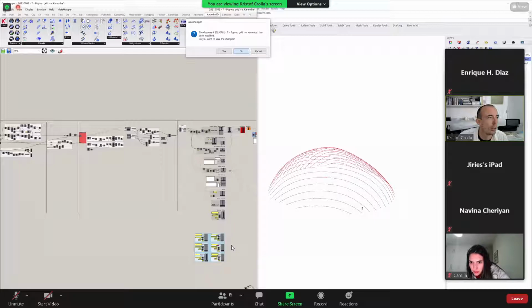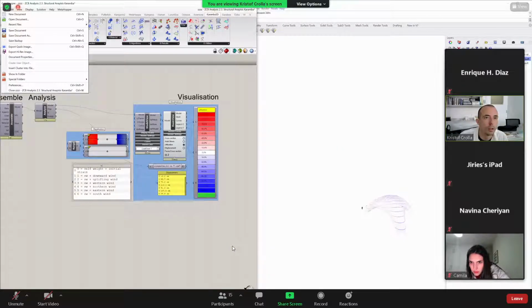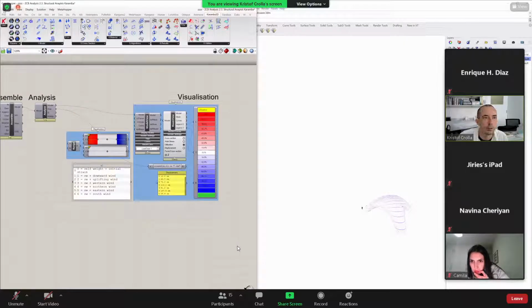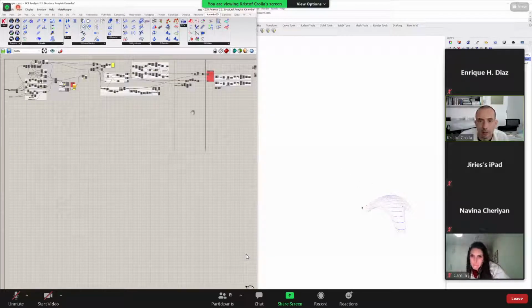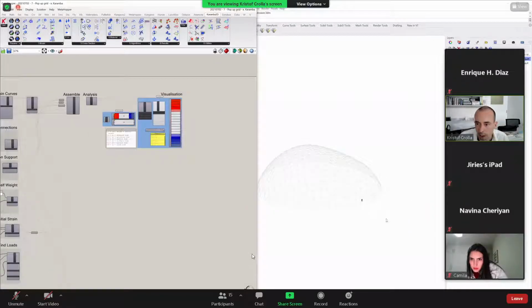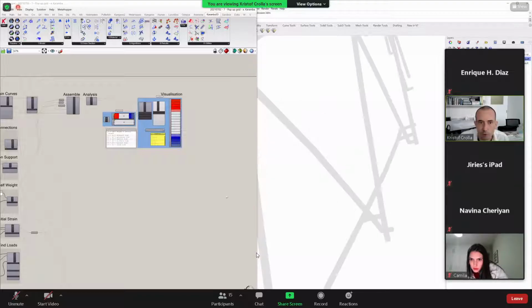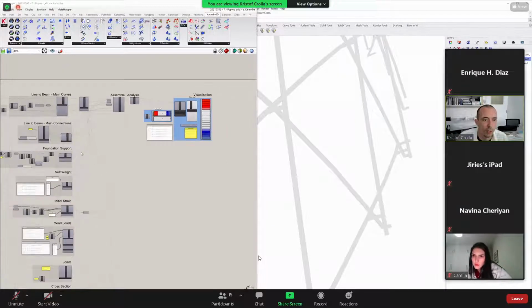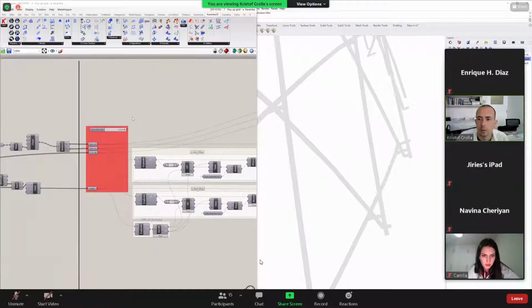And it's all a little bit delicate sometimes, because right now at the perimeter of our beam, of our shell, it's possible that some of the points start to end up in different layers. Let me see. Yeah, it looks like we're a little bit too thick in terms of our offset here. I'm not going to change it right now, but definitely there's a need of calibration there. So this 0.2 is not correct.